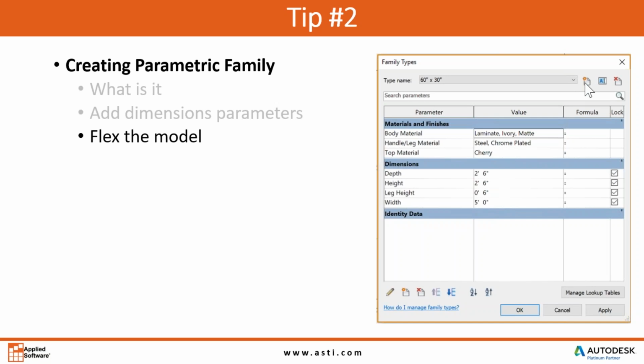So when I place that family into a project, instead of me just randomly being able to type in this depth option here, a random size, I've made it predetermined sizes. I've actually established that these are different type sizes, you know, small, medium, large, whatever it may be, that I can then quickly switch those to. So again, a couple different things for a parametric family.